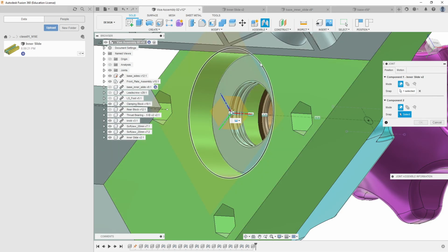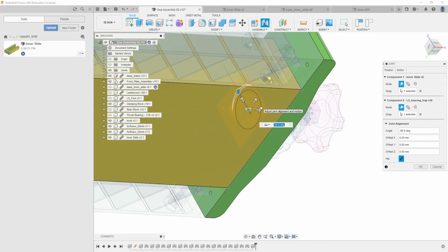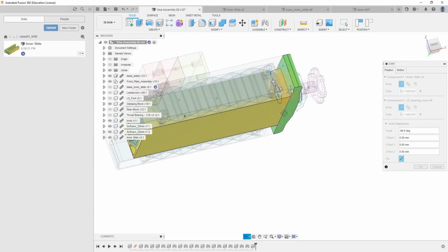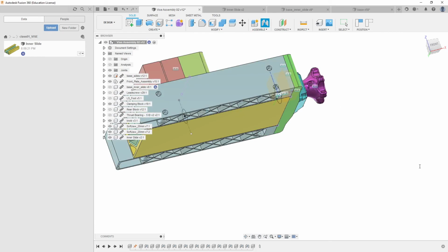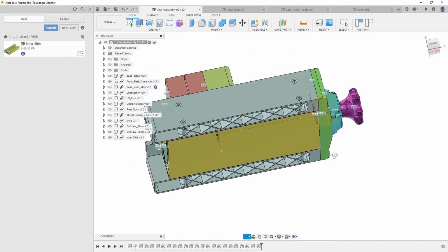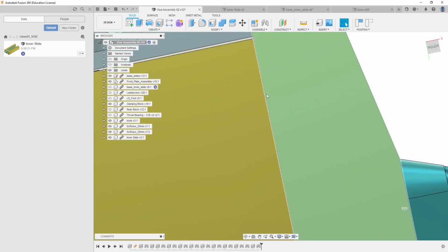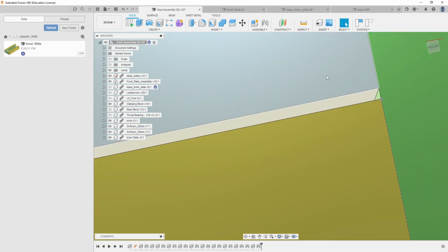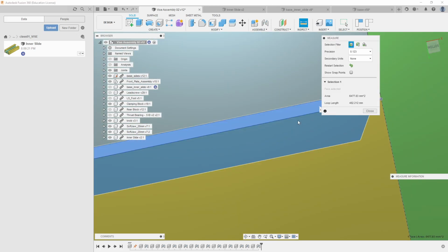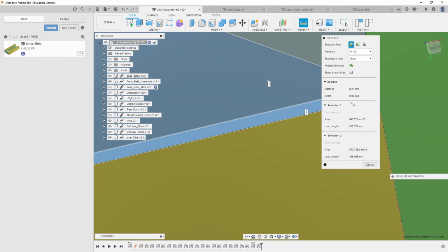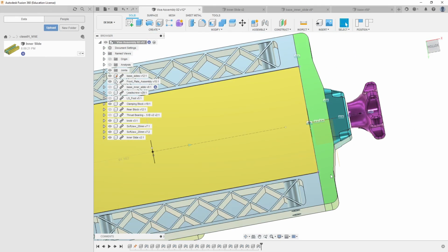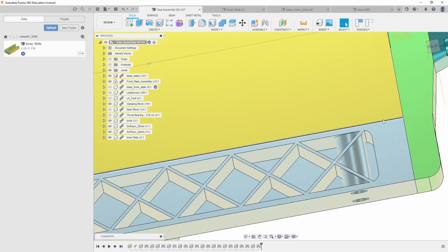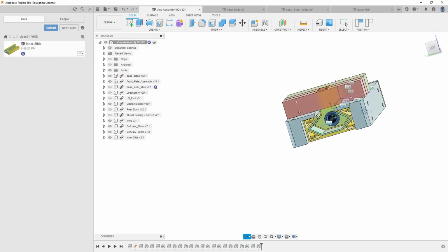Then I come over here. I catch that edge right there, and I hold down Control so I can come over here and pick the little circle in the center, and kapow! They join together. Okay. So then hit OK. And now let's check our work. That should be right smack up against there. But look right here. There's a tiny little gap. That's interesting. How far is that? Let's rotate it around from there to there. Oh, look, it's 0.25 millimeters. We've got a 0.25 millimeter gap as we do over here as well, right? So that's great. That's what we wanted.